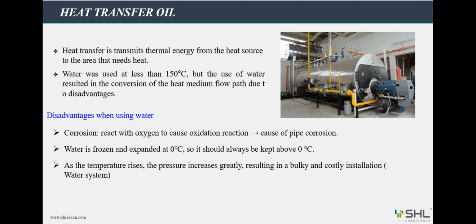and heat loss. Second, water is frozen and expanded at 0 degrees Celsius, so it should always be kept above 0 degrees Celsius. And this makes it difficult to control the bitter cold climate in winter. And thirdly, as the temperature rises, the pressure increases greatly, resulting in a bulky and costly installation, making it much more difficult to install a safe operating system. Thus, to achieve heat transfer efficiency as well as ensure safety, using heat transfer oil is a reasonable choice.